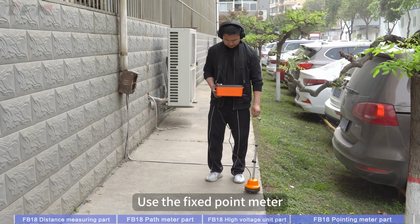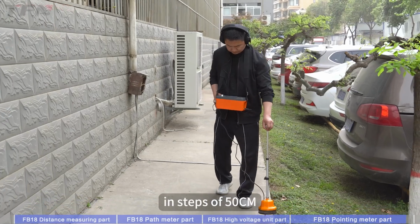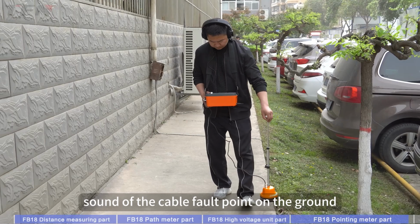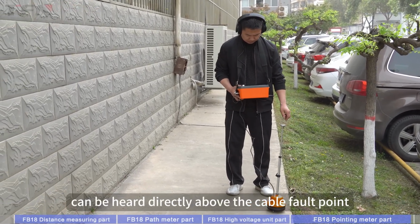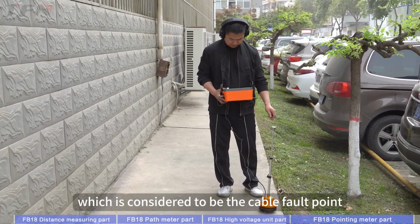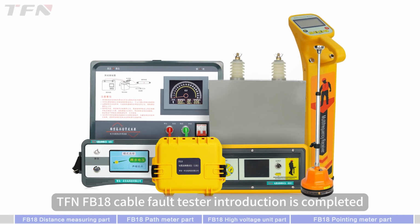Use a fixed point meter along the precise path found by the path meter in steps of 50 cm. Listen to the discharge sound of the cable fault point on the ground. Finally, a clear discharge sound can be heard directly above the cable fault point, which is considered to be the cable fault point. TFN FB18 cable fault tester introduction is completed.